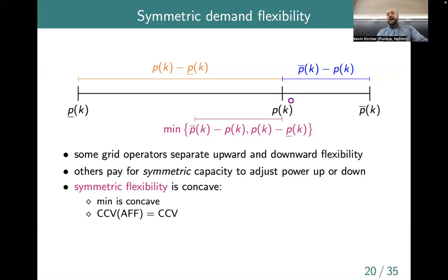And so here, in that setting, P would be like, I might call it your nominal or your baseline power consumption. So you'd say, look, if you don't tell me to wiggle upwards or wiggle downwards, what I'm going to use by default is just this thing P. But you might want to change that operating point so that you hold more flexibility. So if you moved P down, for example, then you'd have more ability to move up to absorb excess power in the grid when that's needed. So yeah, P max here would be some physical limitation probably, either set by what your equipment can do or maybe set by, I don't know, how uncomfortable you can make people in a building or something like that, right?